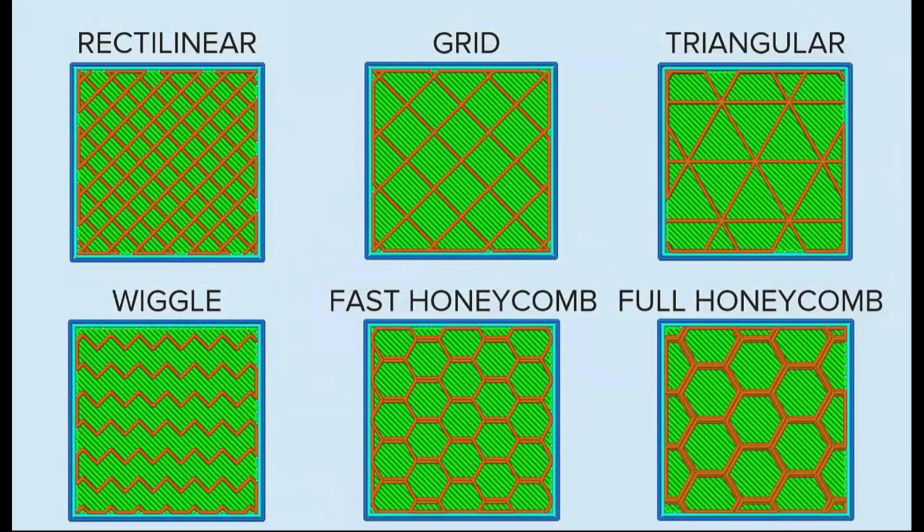Now comes infill, which is one of the most misunderstood parts of slicing. Infill is not there to make the print solid. It's there to provide internal support, resist deformation, and give the top layers something to bridge across. The slicer takes the interior area of each layer and fills it with a pattern. That pattern is chosen based on your settings: grid, gyroid, cubic, lines, and so on.